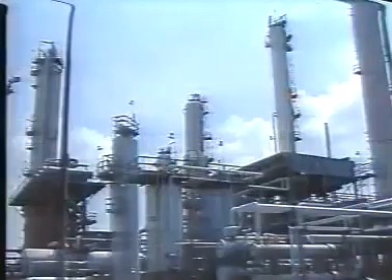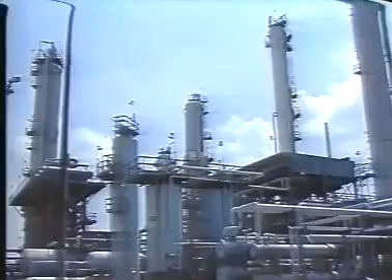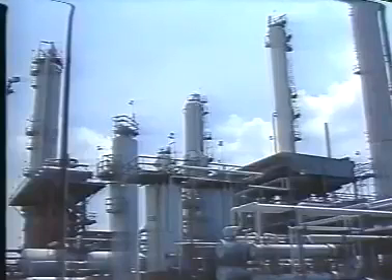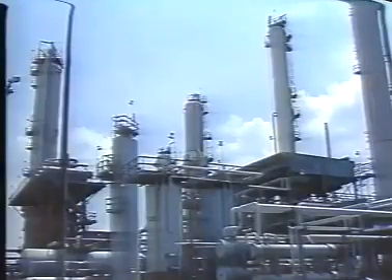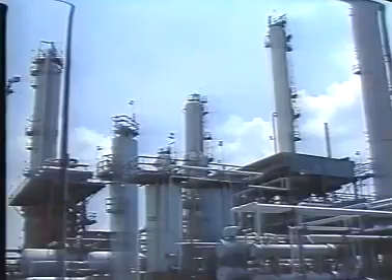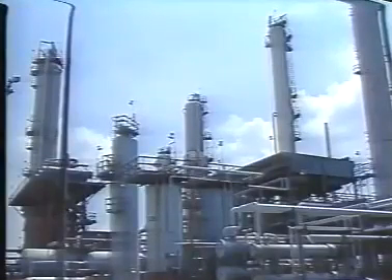A computer, assisted by on-stream process analyzers, is often used to control a chain of distillation columns. When working with a group of towers, a control strategy that considers the entire chain as well as the individual towers is needed. This is because products often have specifications limiting the amount of both heavy and light impurities.